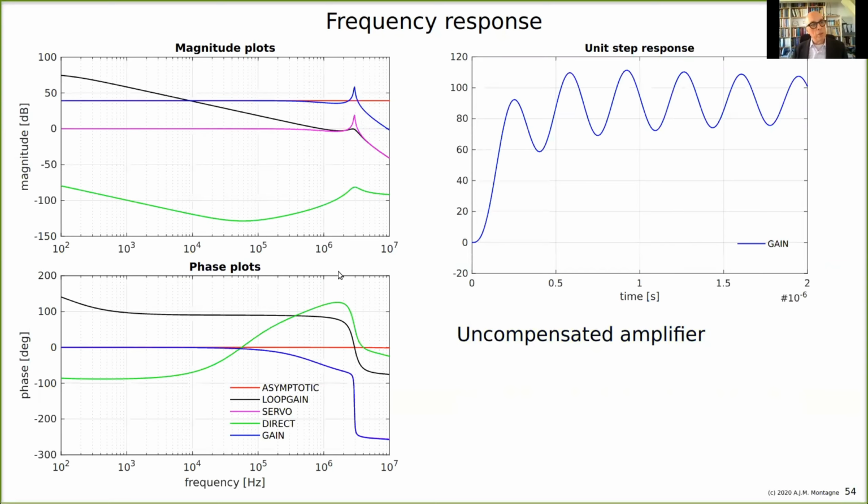And you see, if you make the step response of the uncompensated amplifier, well, if you look clearly, you see that this is damping. The amplitude is getting less, but the step response is really ringing at this frequency. You can count it. This is 1 microsecond per division, so this is 1 microsecond. I must have 3 cycles in 1 microsecond. 1, 2, 3 cycles about in a microsecond. So that's about 3 megahertz.